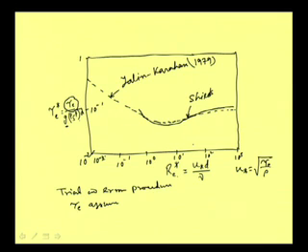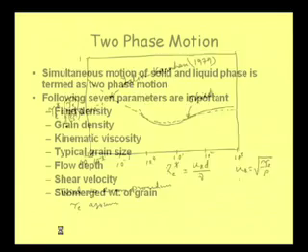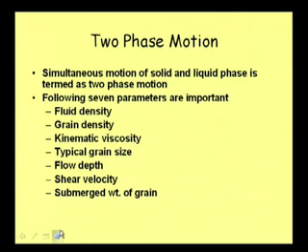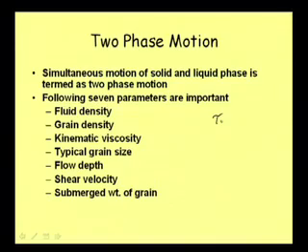Well, with this understanding of tau c star or this tau c shear stress value, now we can just see that when our value of bed shear stress tau 0 exceeds tau c, the particle of the bed starts moving. That is, when tau 0 is greater than tau c, then the particle starts moving.